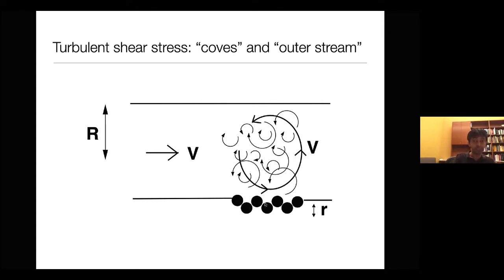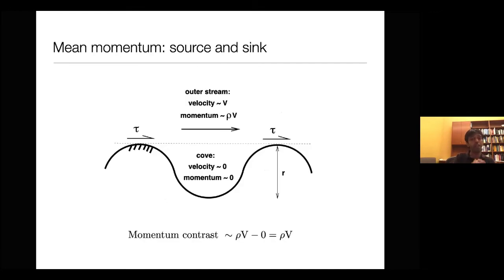Now, this turbulence is confined by this rough pipe. So this turbulence is the fluctuating part of the flow. It is superposed on top of a mean velocity profile. And for the mean velocity profile, I'm going to focus on this region at the interface between the roughness and the flow above. And I'm going to introduce another drastic level of simplification by arguing that if I consider the mean velocity, then because of the roughness, there isn't a mean flow taking place left to right across here.